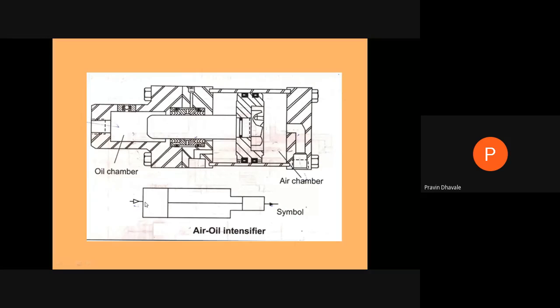In a larger volume, we are supplying the gas or air. Here, this arrow is a blank one, so it is an indication of pneumatic. Pneumatic means gas or air we are supplying. And in this cylinder piston arrangement, see this arrow, this is a filled arrow. It is the indication of hydraulic, that is oil.